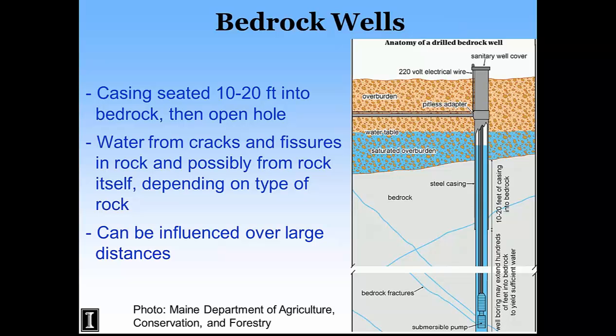That may be a clay or a silt, or a sandy clay, or in some cases even sand, but it's contaminated or has some water quality issue. West of Chicago, I know I use Illinois examples because that's where most of my history comes from, there's a lot of shallow sand and gravel that isn't really usable anymore because it's been contaminated. And so most of the wells go into bedrock in those areas.